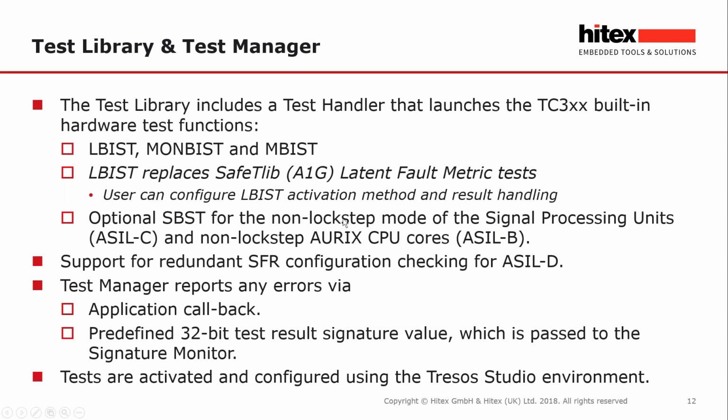The LBIST is probably the most important one, and this is the one that replaces the SafetyLib latent fault metric tests. And within this, the SafeTpack allows you to specify the activation method for the LBIST. This is either at startup or as part of the boot mode header system, so that the processor will have completed the LBIST before actual execution begins.